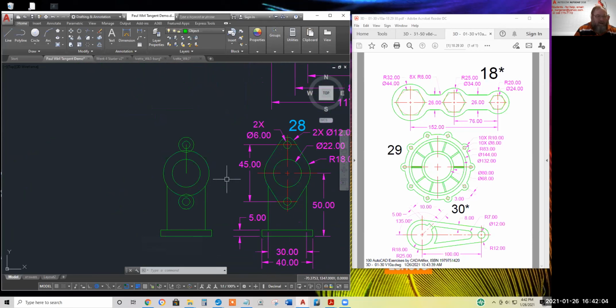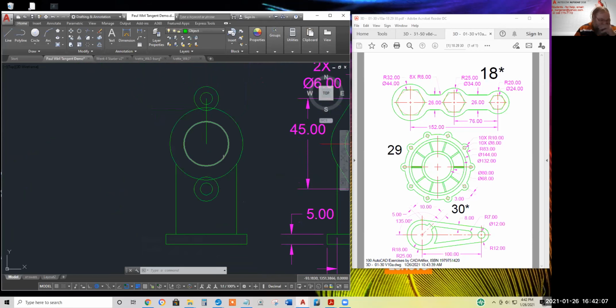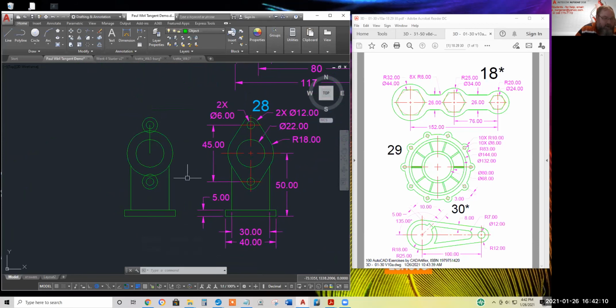I think with guidelines, you can come up with this much of this, I don't know, thermostat housing, whatever it is. You know, I don't have all the guidelines necessary. A couple of you had the bottom of this thing in the wrong place. And I think that was just too hastily working when you didn't draw a guideline from dead center of the top circle straight down and use the bottom of that guideline as the Y coordinate for the bottom of the object.